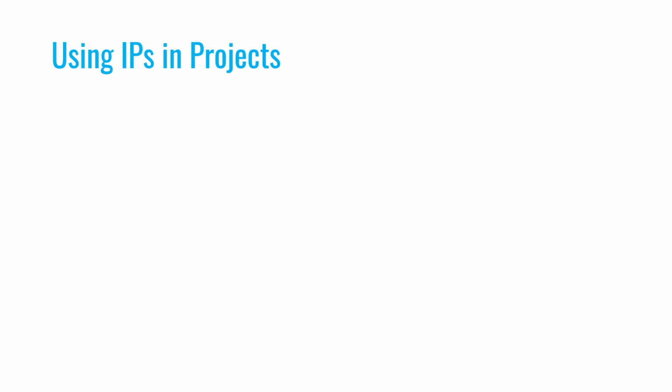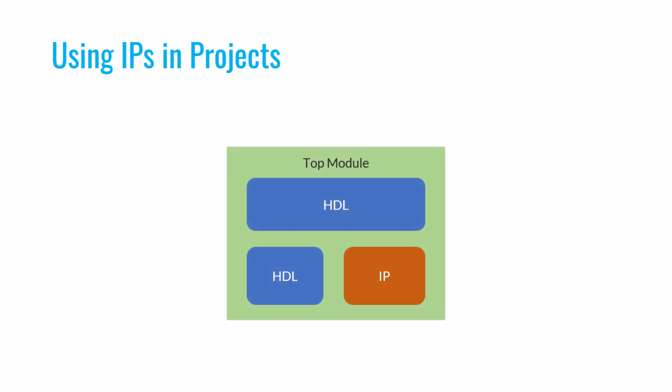To do this, after you've partitioned your system into different modules, you usually write a main module, often called the top module. You then incorporate and connect the smaller modules within this top module to create the final complete module. As you can see in this diagram, a top module might consist of several submodules.